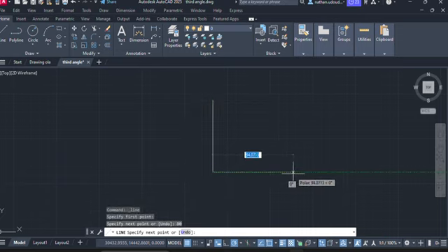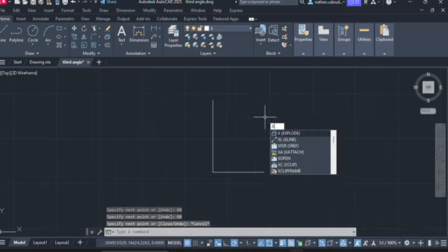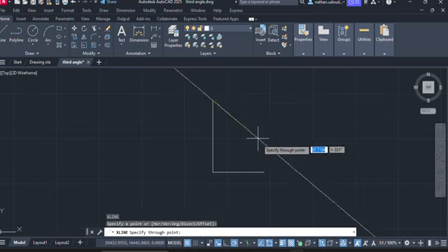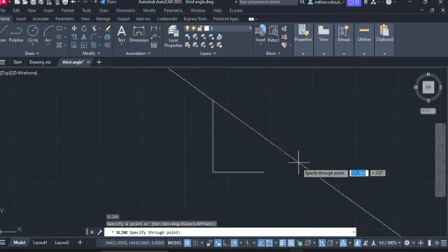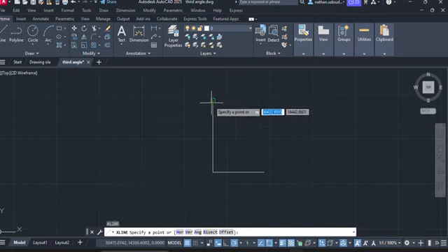While its horizontal distance is 60, enter. And then we don't know this vertical height, but we know XL, enter. The angle of inclination here is 45. But first we come to our polar tracking and then set it to 45 degrees. So XL, enter, that's our construction line.